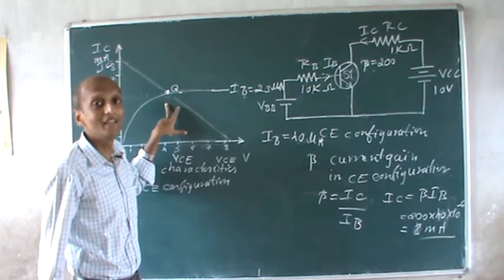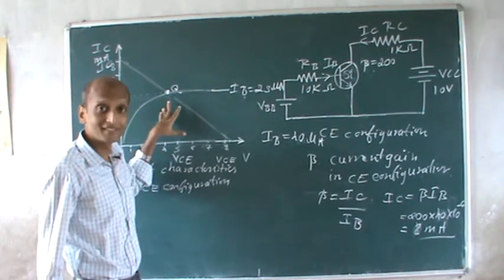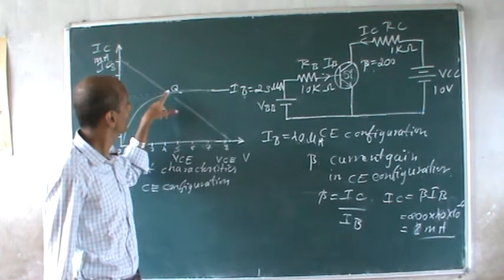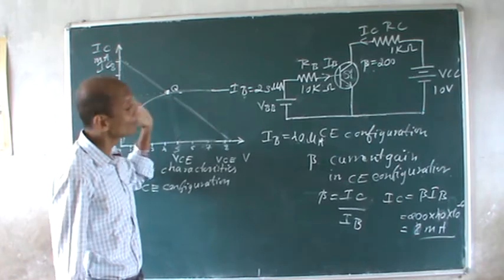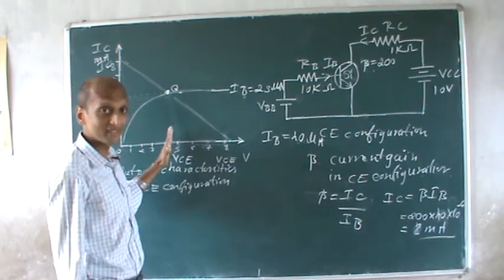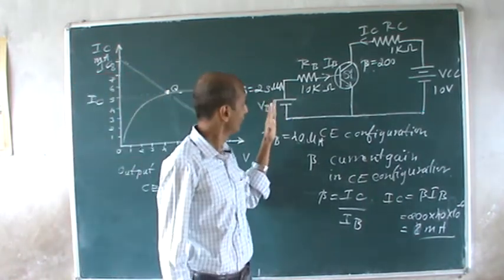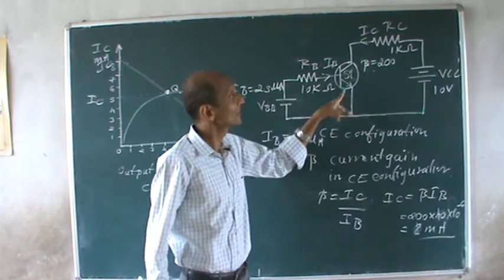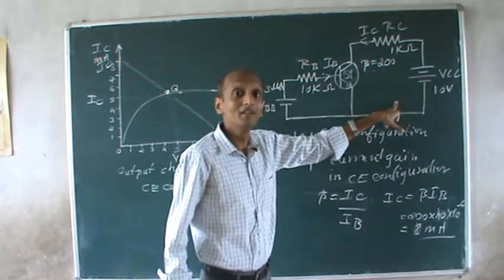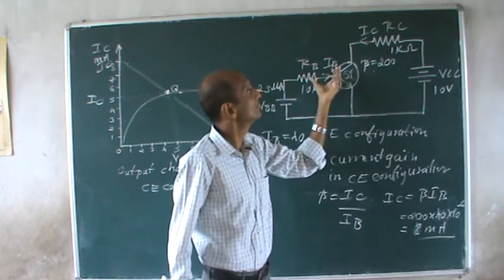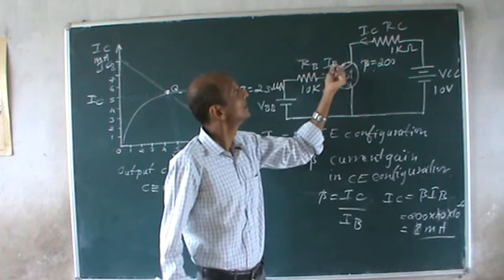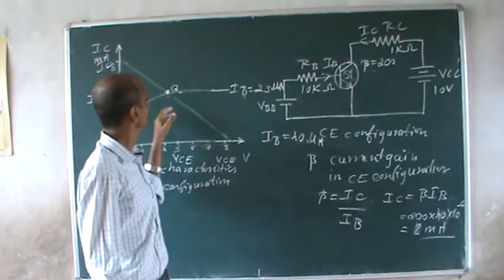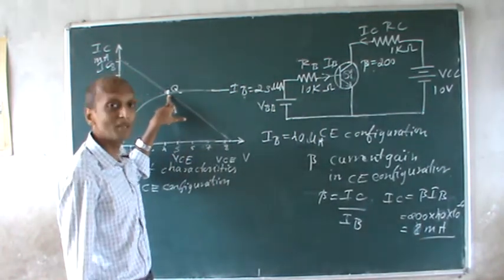So this is very important. For your transistor to work as an amplifier, your Q point should be at the center of the load line. So if you bias your transistor with certain base-to-emitter and collector-to-emitter voltages with resistors of this value, and you make your IB a certain value, you will make your Q point come over here.